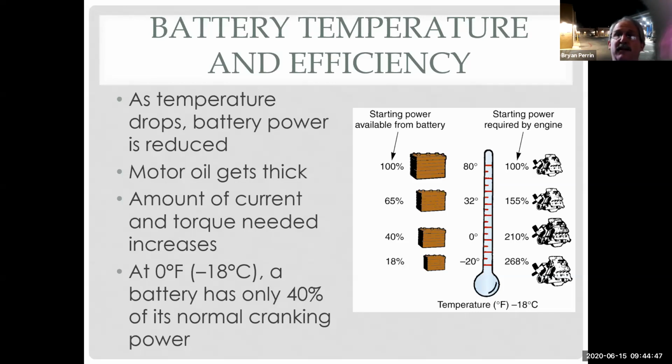Because it has an effect on my battery, and my battery is drained more when I start the car, that means my charging system is going to have to work harder to put power back into my battery. It also means that what? My starter is working harder to turn the engine, so it's going to need more amps. That means the starter's getting hotter. The starter's going to last less time. So you see where everything we do on a car affects other things. Kind of crazy, huh?